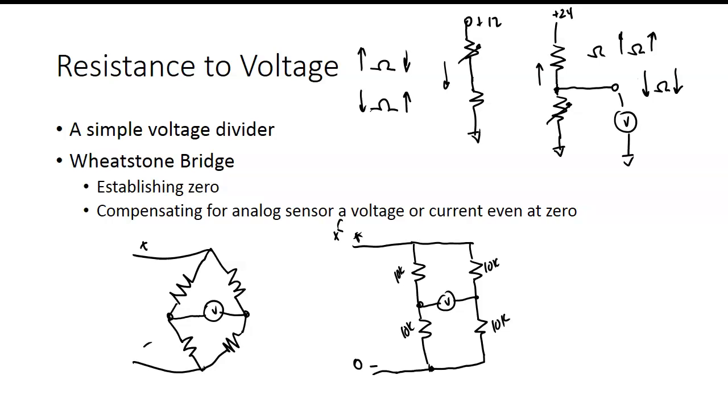Yeah, because we learned in DC that resistors of the same value drop the same voltage, right? So let's do 10 volts instead of 5 volts for this. Maybe we won't be dealing with fractions. If they drop the same voltage and the total voltage has to be applied across the circuit, then each one of them has to drop 5 volts. I'm going to use this one down here as our reference.